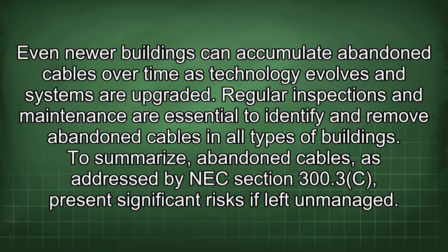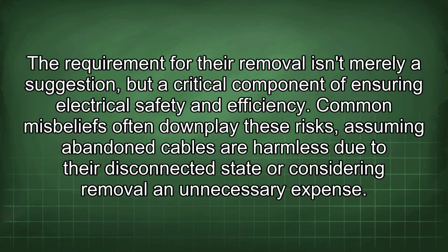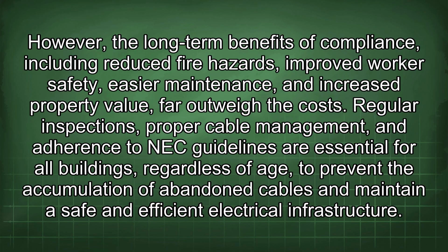To summarize, abandoned cables, as addressed by NEC Section 300.3c, present significant risks if left unmanaged. The requirement for their removal isn't merely a suggestion, but a critical component of ensuring electrical safety and efficiency. Common misbeliefs often downplay these risks, assuming abandoned cables are harmless due to their disconnected state or considering removal an unnecessary expense. However, the long-term benefits of compliance, including reduced fire hazards, improved worker safety, easier maintenance, and increased property value, far outweigh the costs.